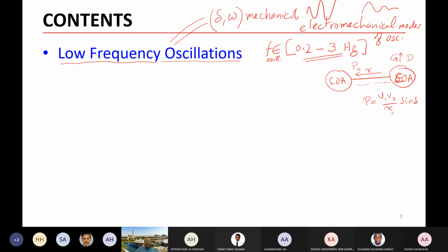And here you have the demand higher than the generation. If you separate this, in this case you may go to blackout here and blackout here. Or at least you have to manage. You have to do some under frequency load shedding, and you have to have countermeasures for this situation. So it is not easy to separate the interconnected systems.